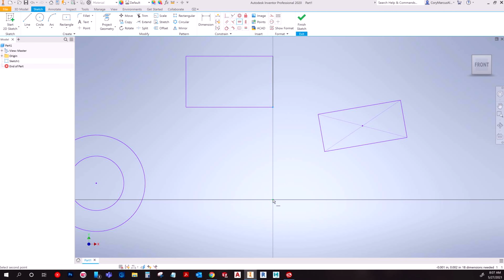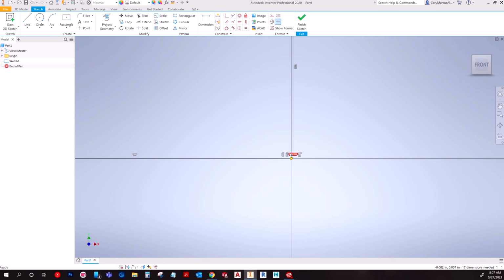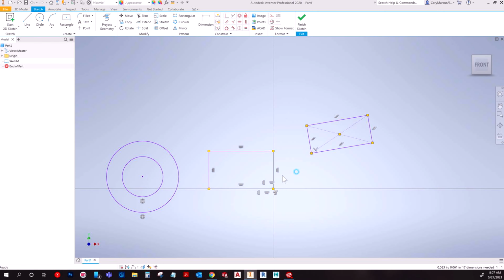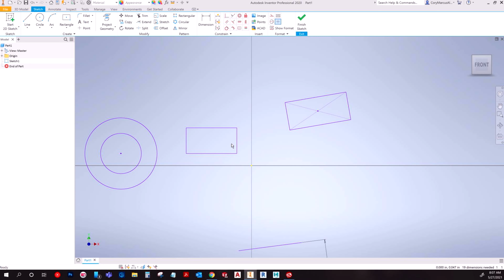But I'm going to do the same thing with horizontal. And just like this, what I've done is pretty much made this corner coincident to the origin, except I can actually delete this without ruining all kinds of existing geometry. It's really easy to go in and delete those horizontal and verticals. So, now I can just tug this guy out. It's kind of a pain when you got pieces on pieces, but now it's disconnected again really simply.